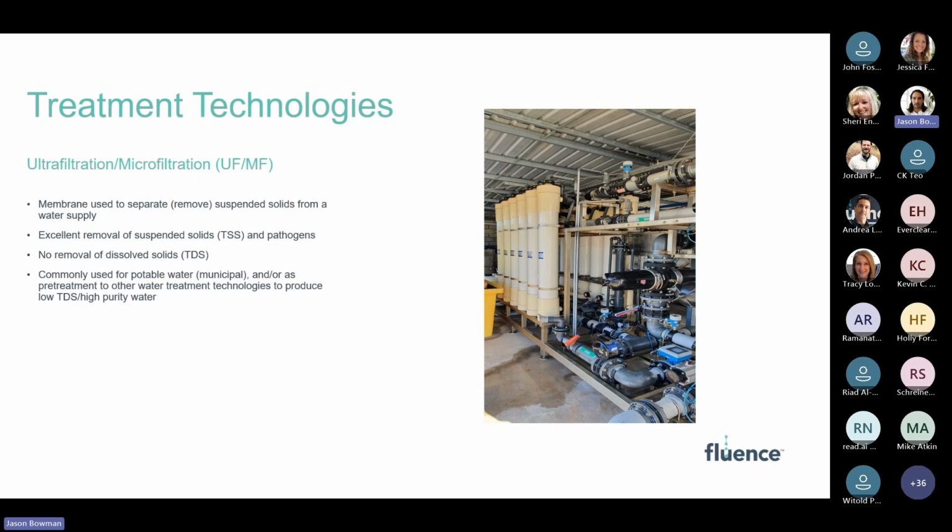I will also note that UF and MF aren't always the only pre-filtration systems that can be applied for suspended solid removal. Media filtration is also an adequate treatment option and at times can be paired with UF and MF for enhanced solids removal in particularly tough waters.